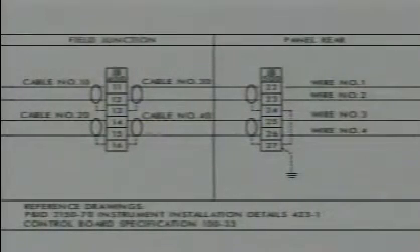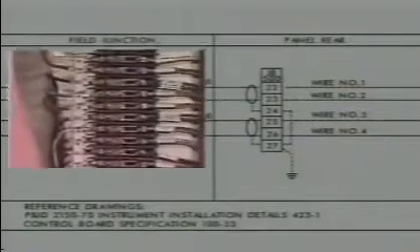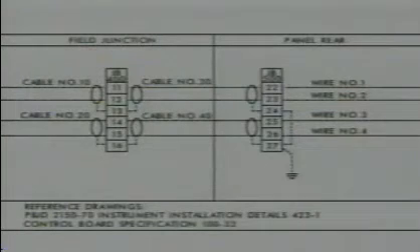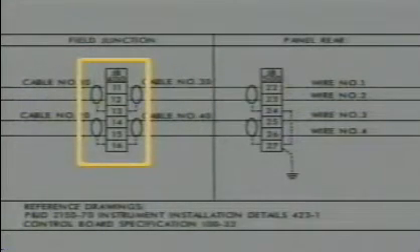Most likely, you won't see any instruments in the field junction area of the diagram, and many of the symbols may be unfamiliar too. This area shows you junction boxes. Junction boxes are the connection points for the signal lines. The junction box symbol and the information it provides isn't usually seen on the P&ID.